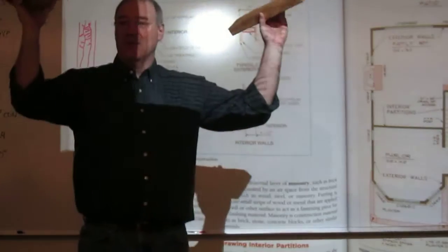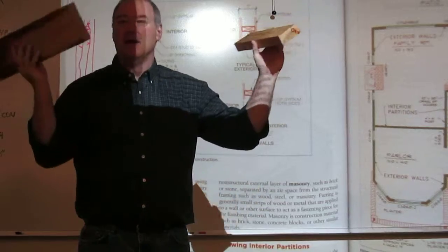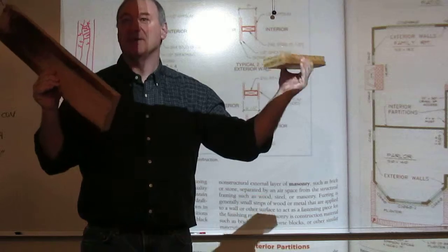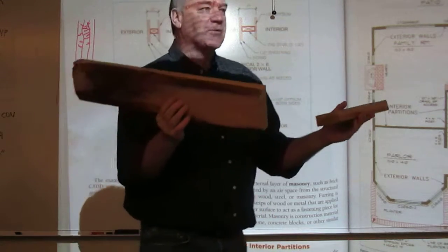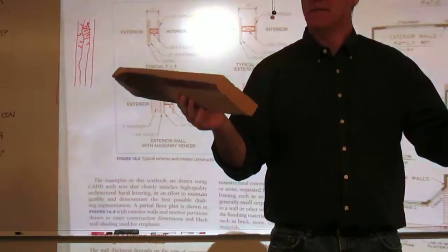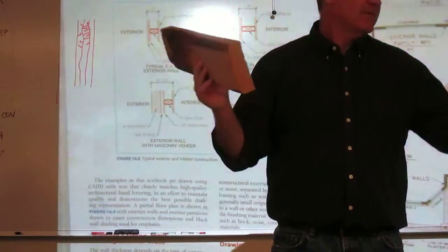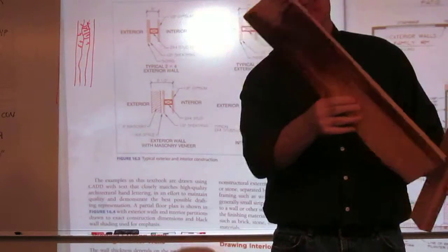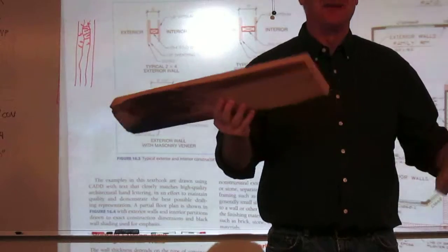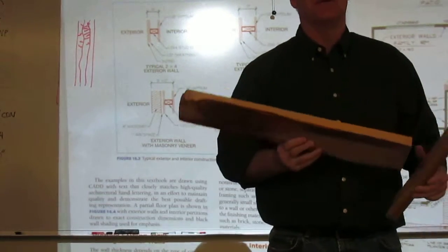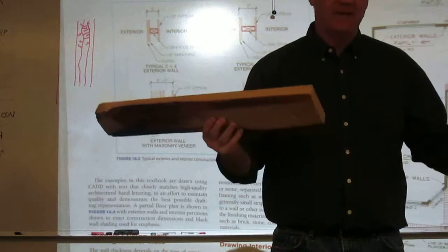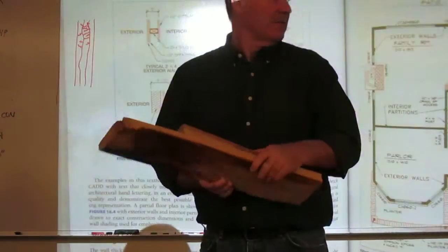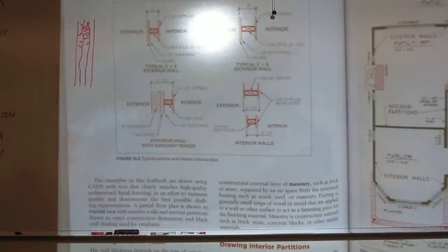If you've never measured one of these, I'm going to pass them around. Take a tape or your scale out and measure these, because you've got to know that these sizes are here. I think there's nothing to drive that home more than sitting here, holding one, and measuring it. What size is a 2 by 12? Okay, supposed to be. It's not always. That's one that gets off quite a bit, but it is supposed to be when you purchase it. Okay. 2 by 10 would then be 1.5 by 9.5, and so on through the deal. Okay, I know those. I'll pass these around. You should measure the sizes.